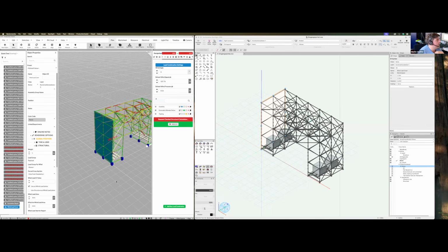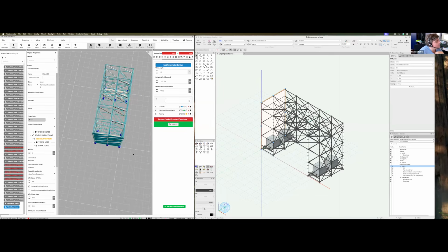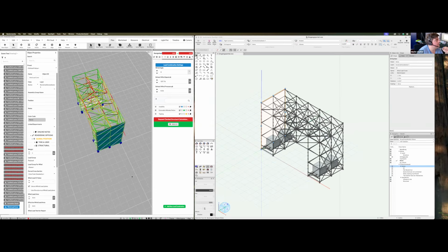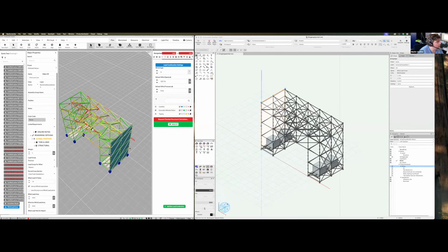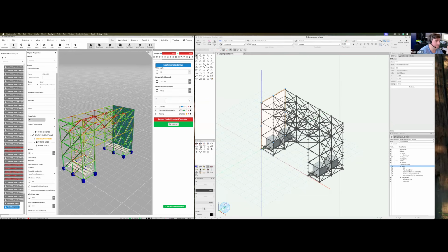So there is something else happening because the wind in here is flowing around the structure. And what is happening is that directly behind the structure, it's basically pulling the wind away from the structure. So it's a little bit like a plane. So the wind is flowing along the thing, and like the plane, the structure is also pulled up. And that is what is happening here. So there's a part of the wind load that gets applied to the front, and a part of the wind load that gets applied on the back.